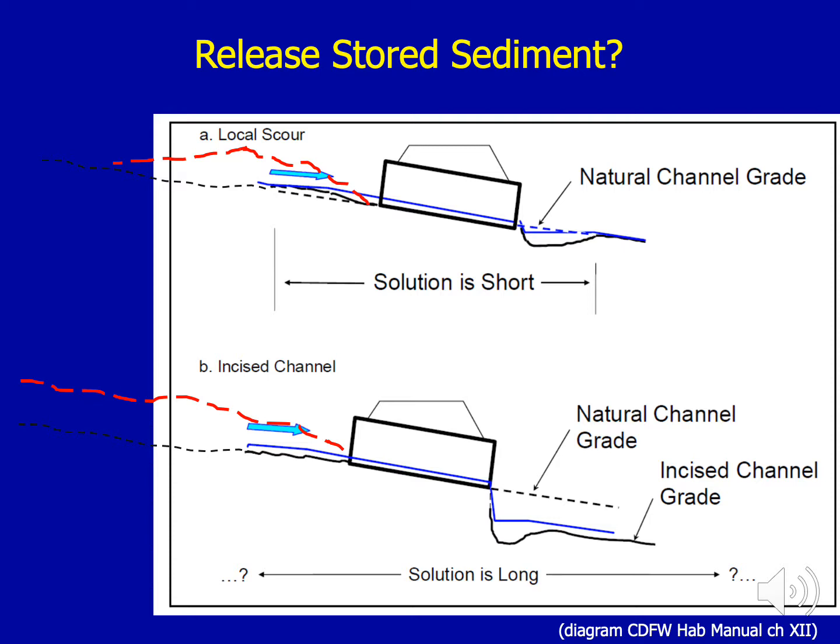First order question is to answer, what is my situation? Is it just localized aggradation happening upstream? Or is it such that we have systemic aggradation happening upstream, and the upstream channel has likely adjusted its banks to this deposition? How do we know which one we're in? Adequate long profile, going up far enough upstream.